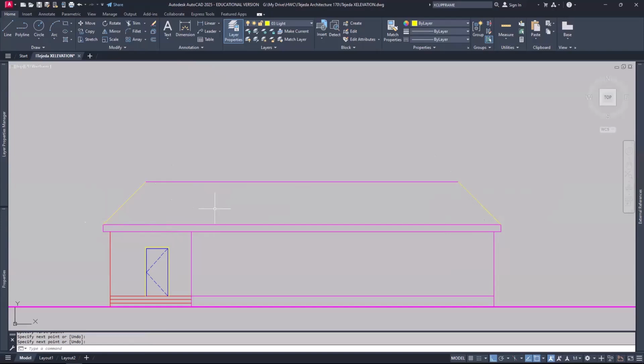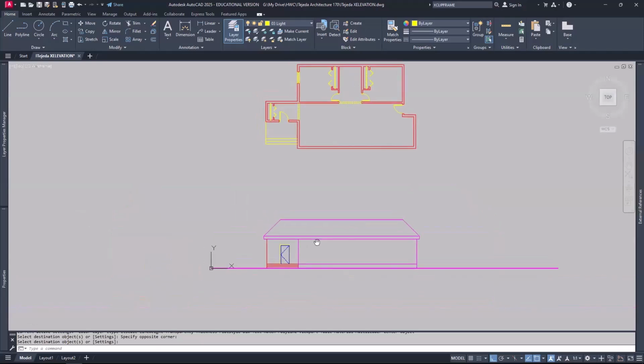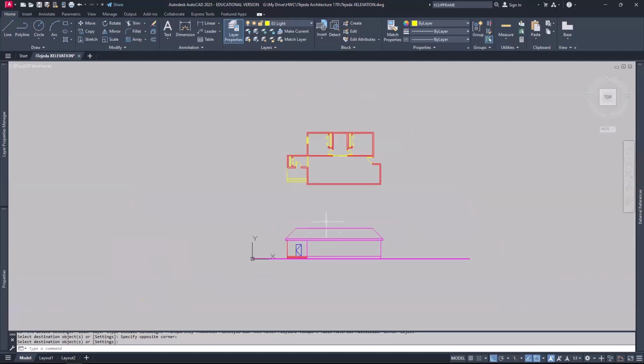It doesn't look like it's matching my SketchUp model, and I'll check that model later. But for now, I'm just showing you how you would do it. And then I'll type MA to match the properties of this line, and I want to make it apply to both of these, and enter. That's the beginnings of my, I'm going to call this one my front elevation, if you want to call it that. Or, when we start annotating, we can maybe call it the east, west, north, south. We'll see. But it's the longer of the 2 elevations.